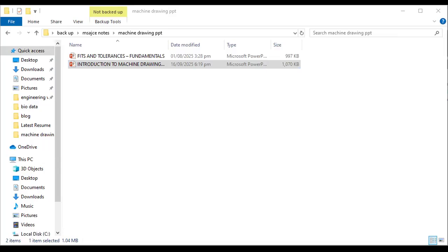So here comes the basic welding symbol. What are the necessary things that are included in the welding symbol as per the standards? An arrow line, which represents the area to be welded, then a reference line, then a dashed line, then a symbol which is closely represented above the reference line. So these are the various classifications of welding symbols according to the different types of welds, as shown in the physical representation.